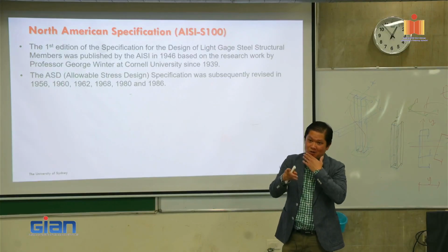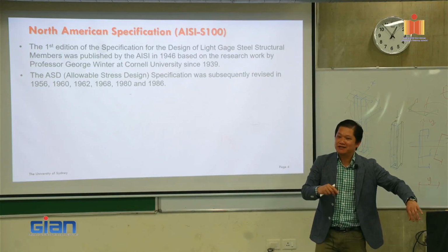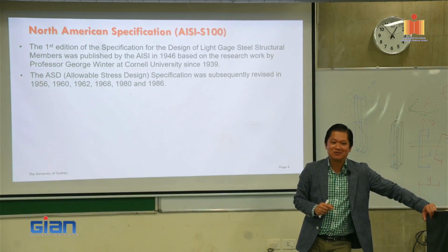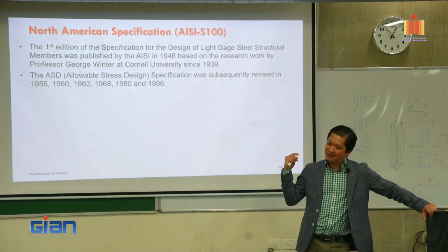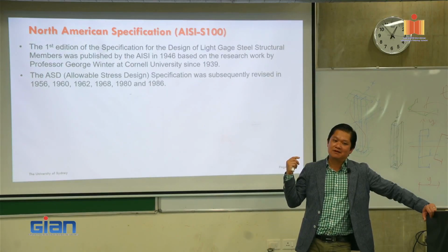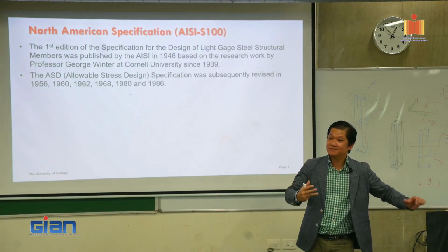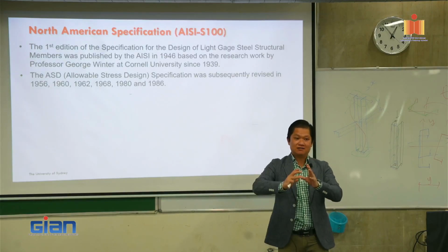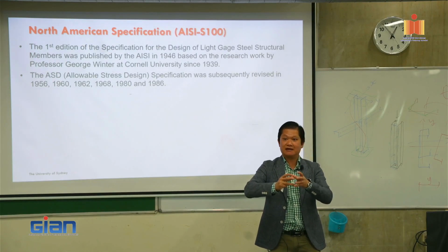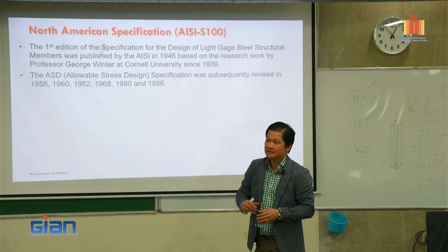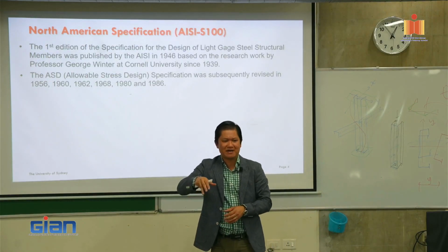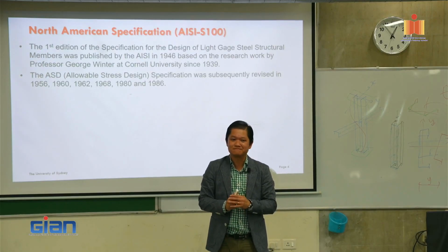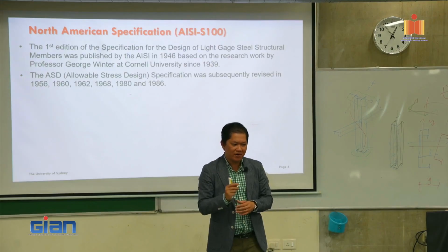Right. So I got your point. I have one of my PhD students now working on biaxial bending. We hope that we can do it. It's not just about purlins, but about columns as well. If the corner column is a channel section, when you've got wind this way and wind this way, the column is subjected to biaxial bending, and of course compression action as well. Very complicated in that way. So your point is very good.